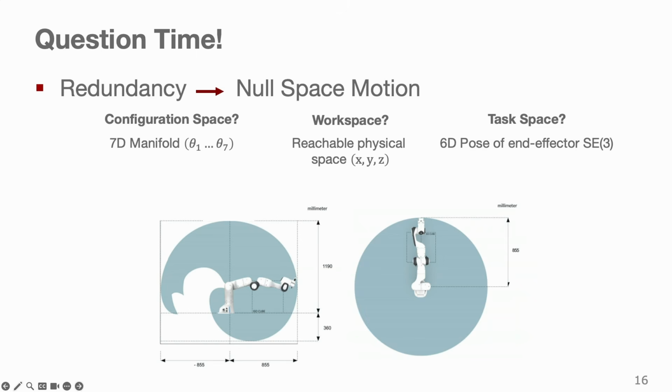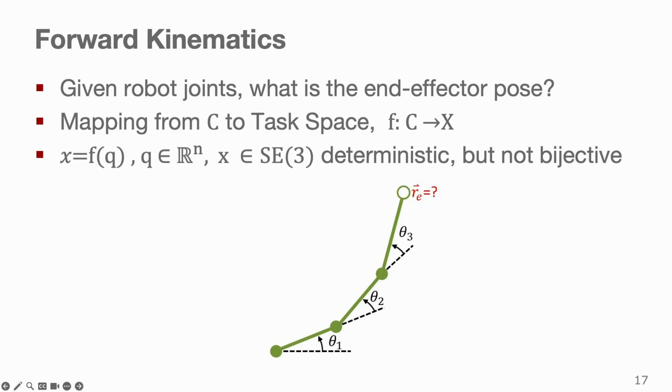One important thing that we will be covering now is that, as we discussed before, the task space is smaller than the configuration space, and this leads to redundancy and null space motion. So for example, if the robot is holding a mug of coffee perfectly still, there are many different ways for it to move the elbow while maintaining the same fixed point of the end effector in space. This allows you to plan around obstacles, for example.